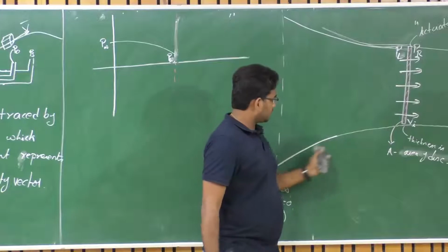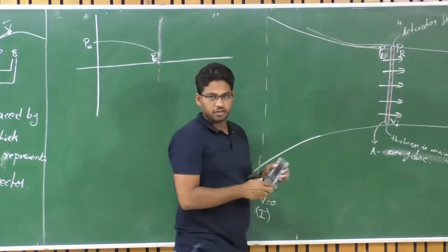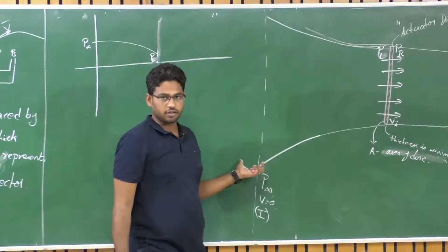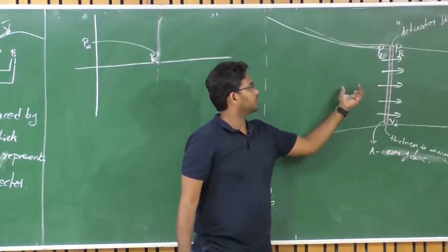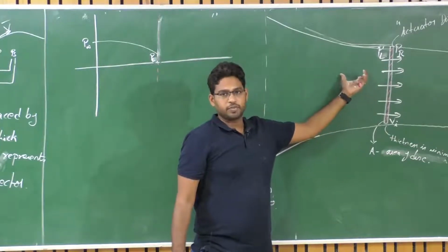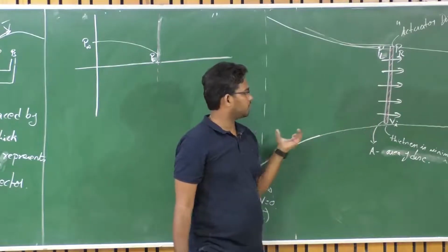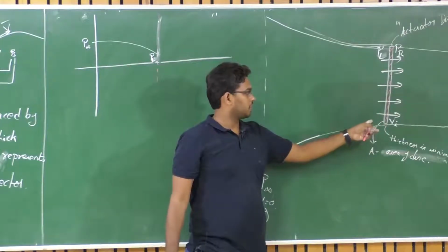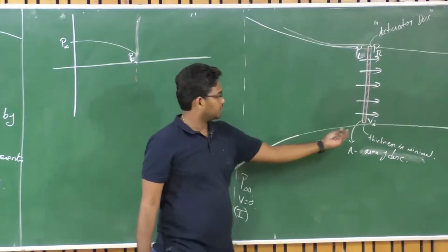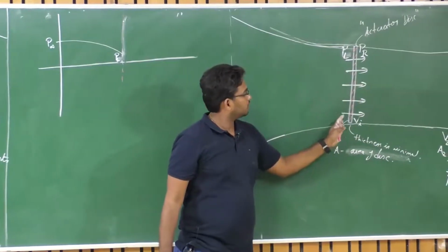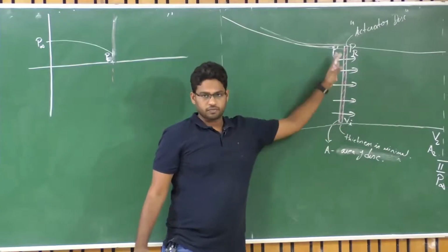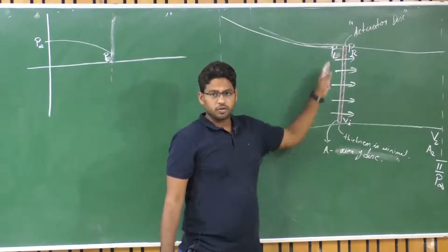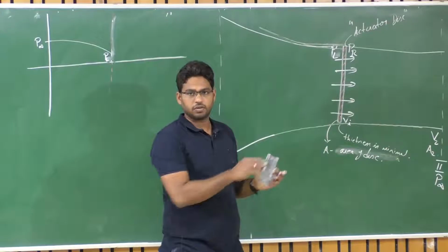See, in this particular portion there is no addition of energy, isn't it? So according to Bernoulli, the static pressure is now converted to some static pressure plus dynamic pressure, because the flow is set into motion and is moving. Almost close to this disk, ahead of the disk, let us consider it is moving at a velocity Vi, and we consider the disk thin. So this velocity remains constant across this section, because the area of the disk is very minimal. According to the continuity equation, this velocity remains constant across this disk.